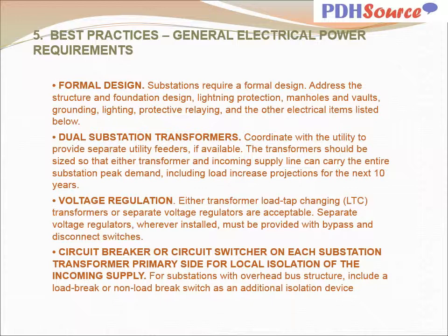With regard to circuit breaker or circuit switchers on each substation transformer primary side for local isolation of the incoming supply. For substations with overhead bus structure, include a local load break or non-load break switch as an additional isolation device.